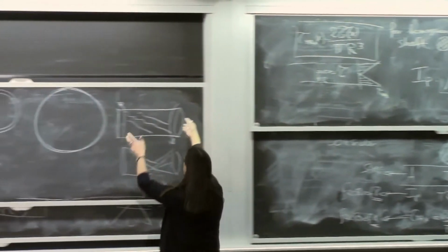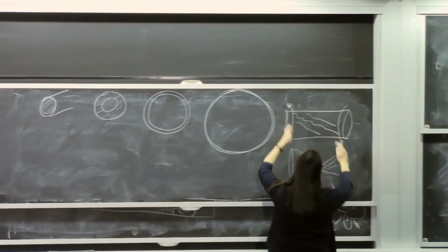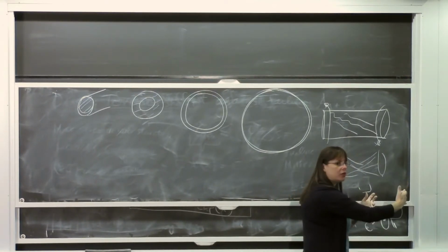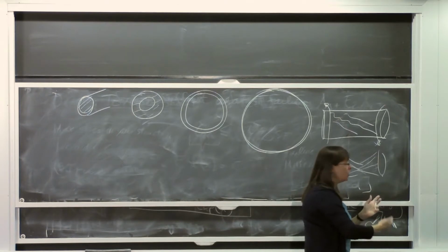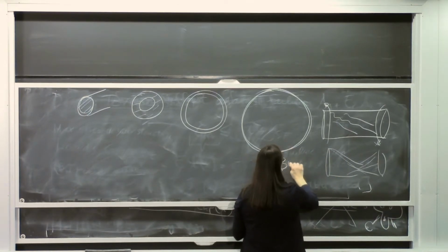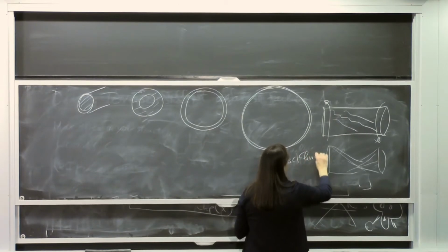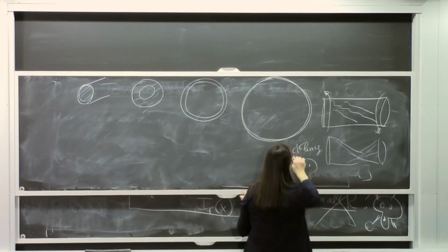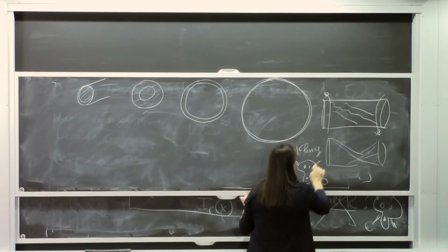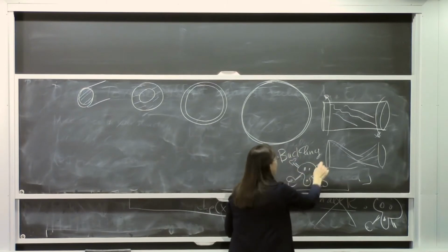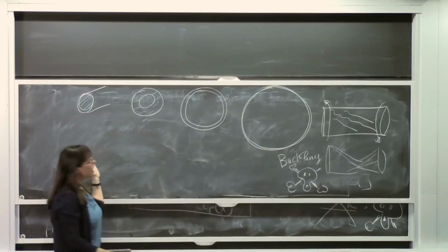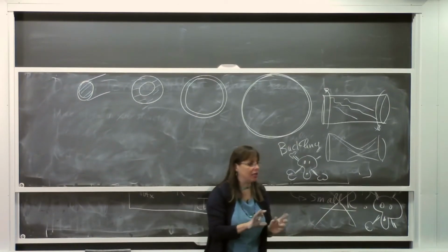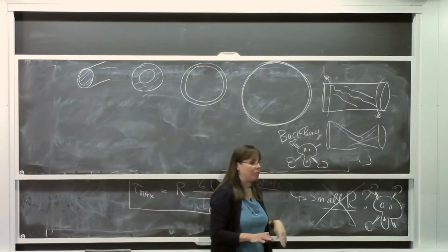Now, what happens with the soda can is something that looks like buckling. You rotate, rotate, rotate, all of a sudden, boom, it goes, and it wrinkles all over the place. So this is a buckling instability. Buckling is very bad. The death from buckling. So you can only go so far with this idea of making things thinner and thinner, because if you make them too thin, that happens.